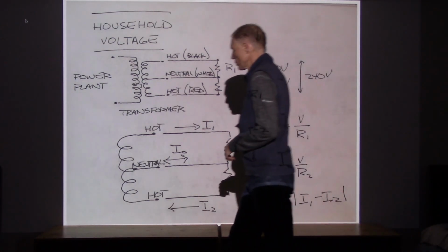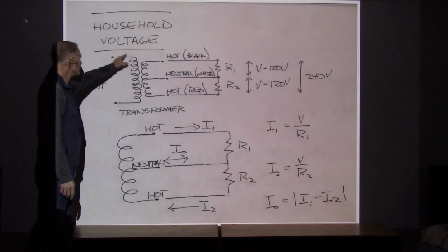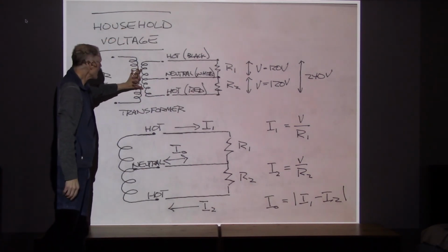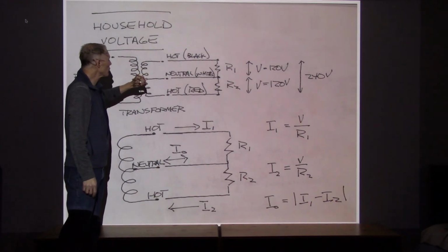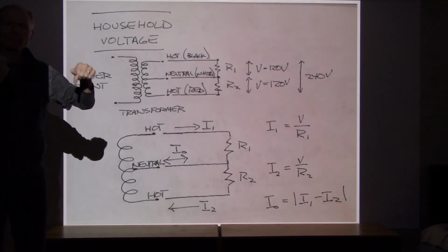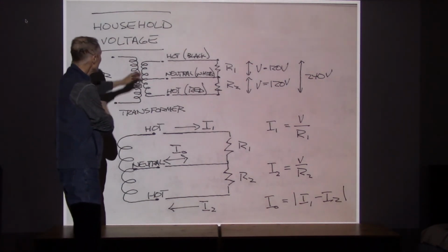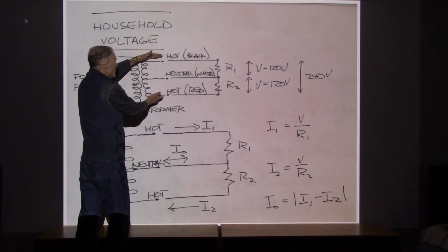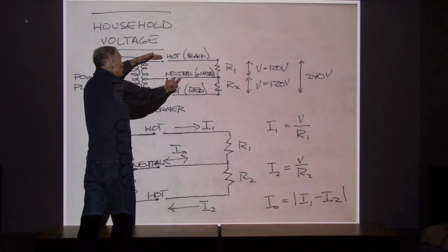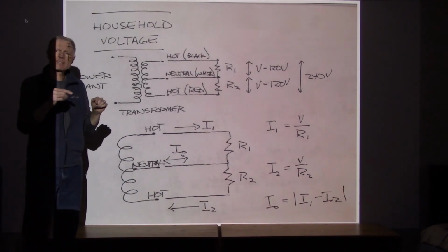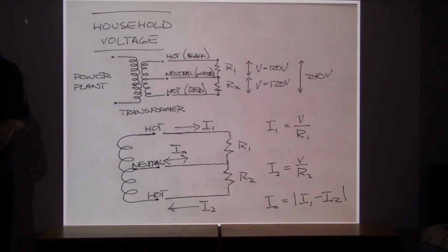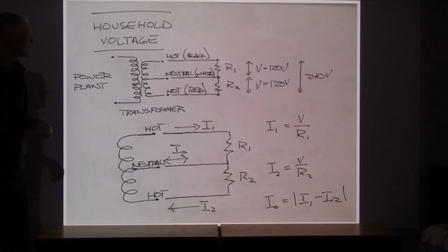Now when the current does come into your house, here is this 2400 volt line, and here's a transformer up in the neighborhoods. This side is at 240 volts, so the wiring coming into your electric box in your house or your apartment is coming in at 240 volts, but that's split. What they do on that side of the transformer is they don't just have these wires at 240, but they have one in the middle called the neutral wire, which officially they designate as 0 voltage. This neutral wire actually gets grounded, literally, into the ground. You run a wire with a long copper grounding conductor and pound it into the ground so that this stays at neutral voltage.